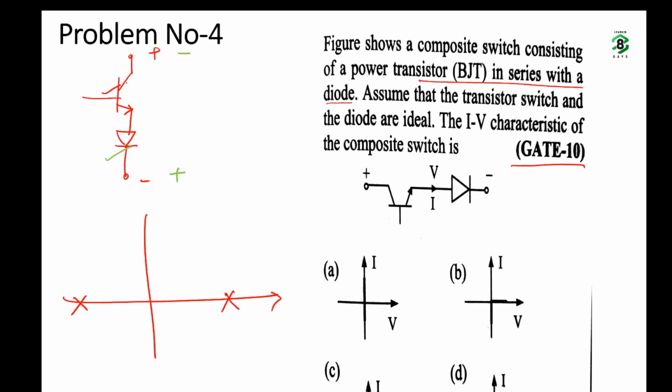Okay, now see the current flow. If I see the current flow in this direction, then this current will be allowed by this BJT as well as this diode. Current flows through this diode, positive and entering. Here in the question, the current I is entering the anode, that's why I have shown it, and this current direction is the same as the current direction that we have considered.